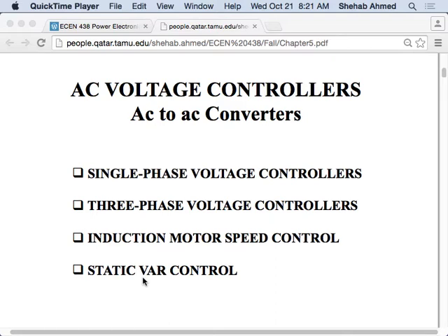So instead of these manual switches, we can use power electronics. If you use power electronics, you don't need to switch the full capacitance in and out, right? Remember, we have an SCR, right? With an SCR, I can put only a small portion of the input voltage across my load and keep increasing that. So I can increase that and decrease that. I don't need to switch the full bank of capacitors in and out, right? It's called a bank of capacitors. Capacitor banks, that's what they're called. It's the terminology that we use.